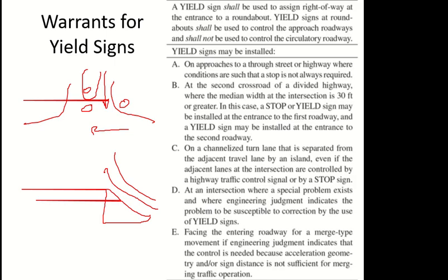So I'll take the right turn from here, and this is the highway for street. When I'm making the right turn, I have to merge into this lane. So you may give a yield sign here, because if there's somebody already in this lane, then this guy needs to wait. So you may provide a yield sign over here.